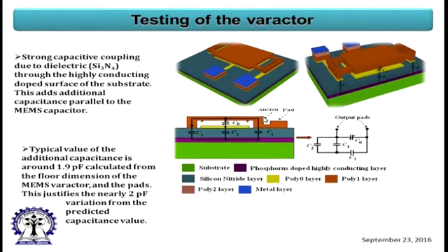So when you touch the probe, how many capacitances actually come in? You have C0, which is your desired capacitance, plus all these capacitances together. If you look at the expressions, I need a femtofarad capacitor, but around 1.9 picofarad is coming in just as a parasitic substrate capacitance.